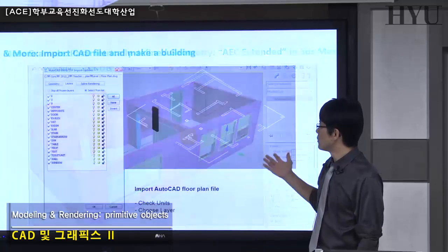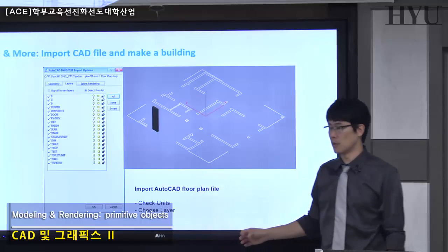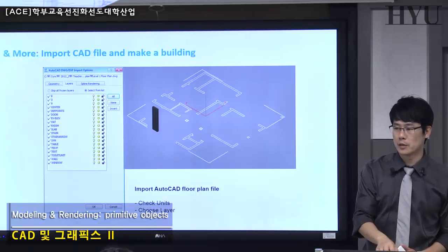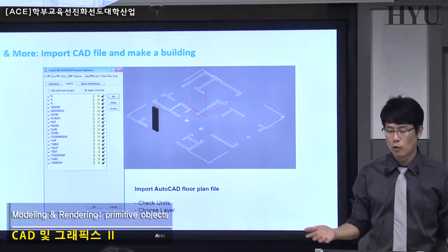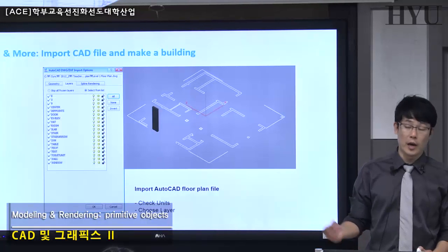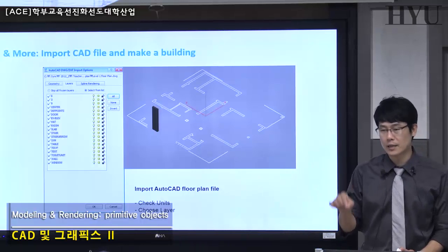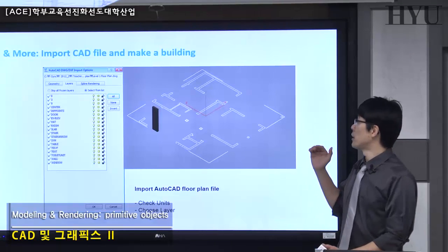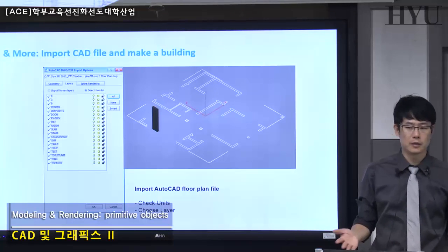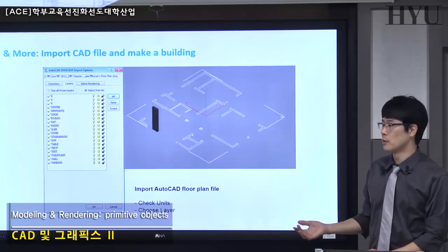Another way is to simply import a 3D model, a SketchUp model. You can easily drag and drop your SketchUp file on top of your 3D Max, and then you can take a look at almost the same geometry as in SketchUp. You can download a 3D Warehouse model in SketchUp format, a .skp file, directly into 3D Max, and you can reuse that geometry in 3D, not 2D, okay? So reuse is one good way. Another one is